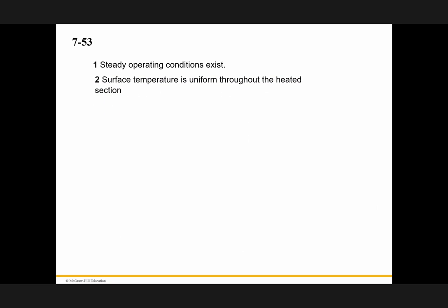And then we start from here. A steady operation. We assume the velocities remain constant. And then we assume also the temperature of the plate remains as it is. It's not changing, not a function of time. Surface temperature is uniform throughout the heated section, everywhere from when it starts to the end.